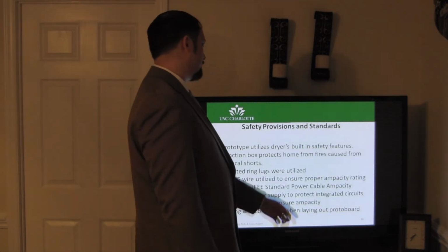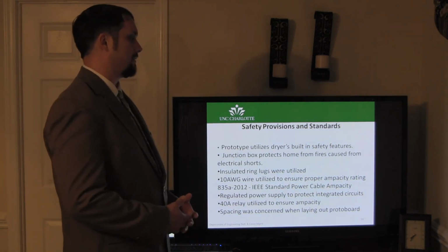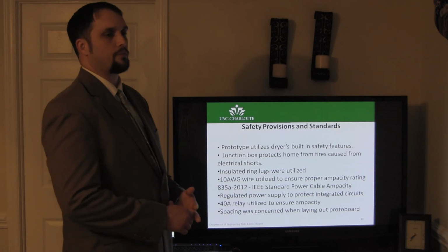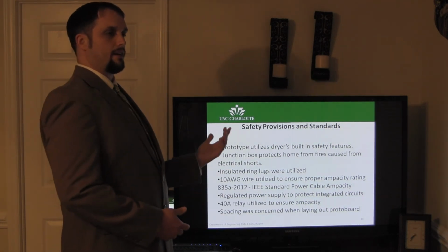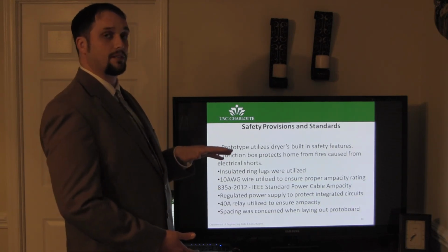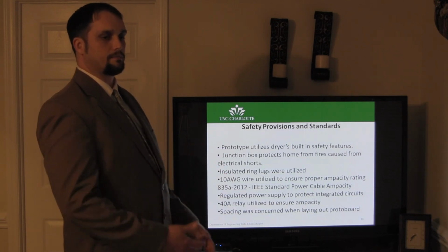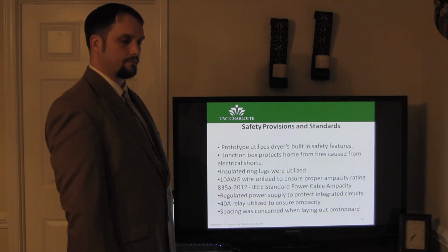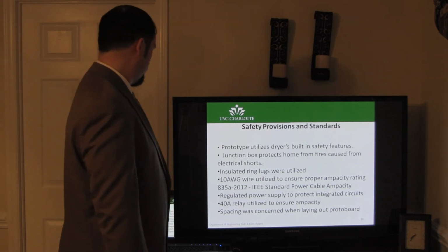Spacing was a concern when laying out the prototype board, the proto board. So basically, what I iterated earlier is that everything that's high voltage is on one side of the proto board, and everything that's lower voltage is on the other side. So to prevent any flashovers or arcing there.